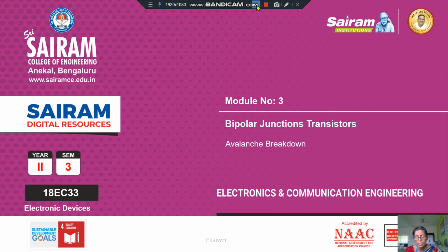Similarly, the second one is called base narrowing. In that case, when the collector to base junction is reverse biased, the reverse biasing modulates the base width. Because of that, there will be an increase in the collector current. When the collector current is increased to a certain extent, punch through happens.